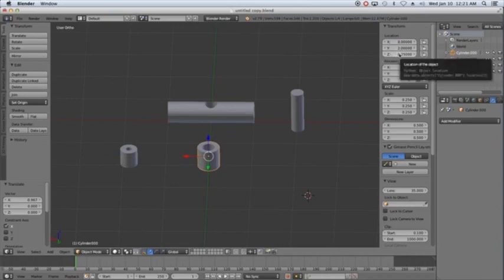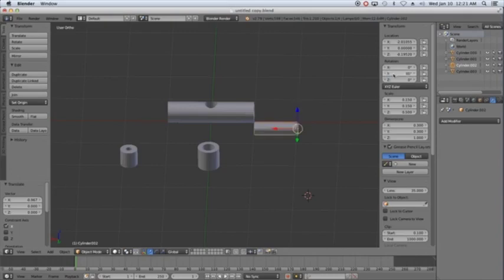I'm going to take my 3 millimeter cylinder, rotate it 90 degrees around the y-axis, and put it at that same location. Let me remind myself what it was. It was 0.25. So x of 0, y of 2, and center at 0.25.